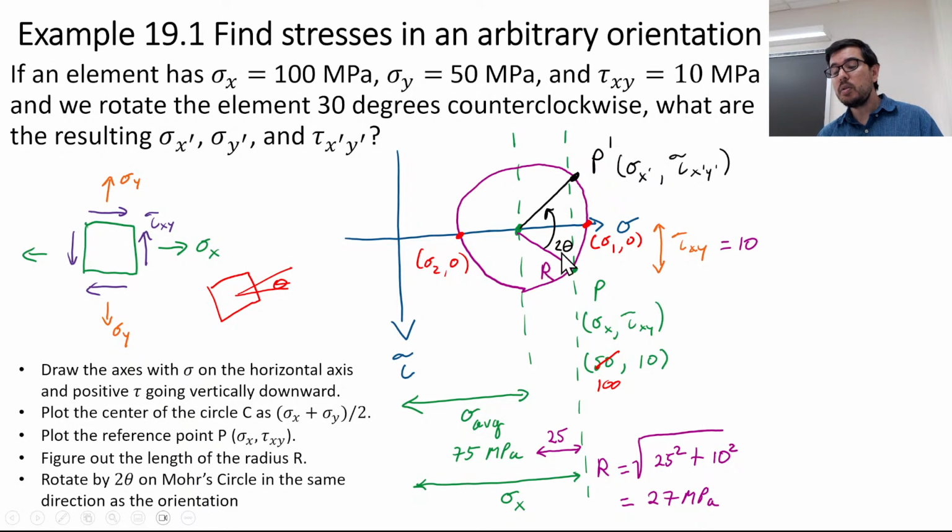And then to get to principal stresses, I had to rotate some amount. If this angle in here were like 60 degrees, then it would correspond to a theta equals 30 degrees of rotation to get to the state of principal stresses. I rotate by a clockwise amount, right? Half. Remember the 2 theta that we were talking about?